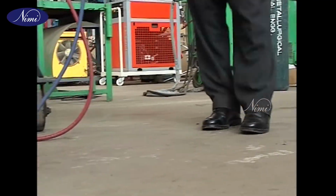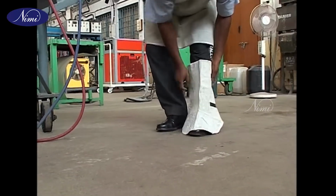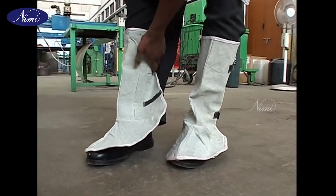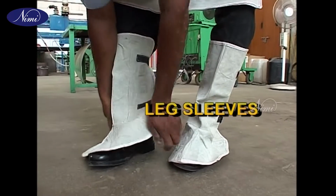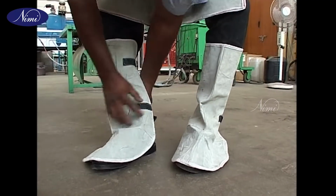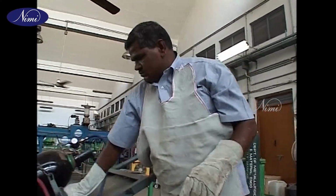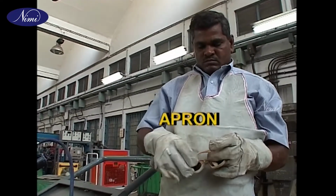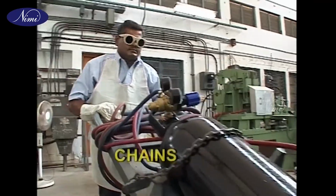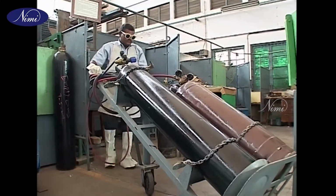Now, let us understand the safety ways for gas cutting. The gas cutting operator has to fully protect himself with safety wear before he starts a gas cutting operation. What he now wears is known as leg sleeves. This protects his feet. Then he wears gloves on both hands to protect his hands. An apron to protect his body has already been put on. He wears goggles to protect his eyes. You can see that chains are put on the cylinders to prevent them from falling when the trolley is being moved.